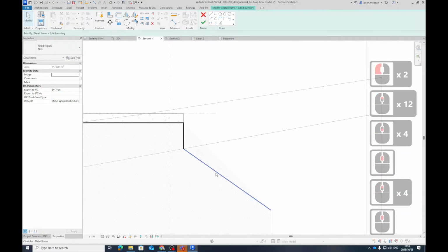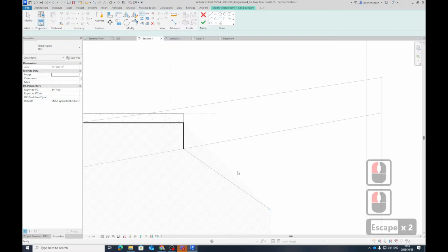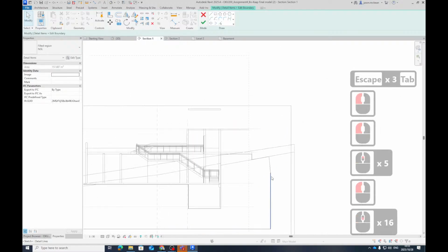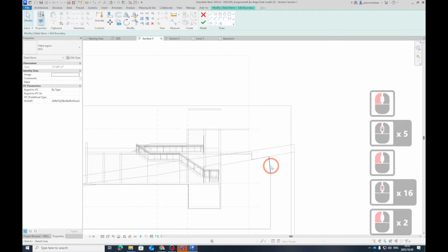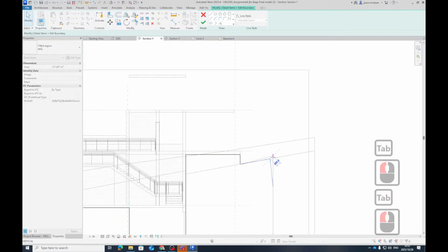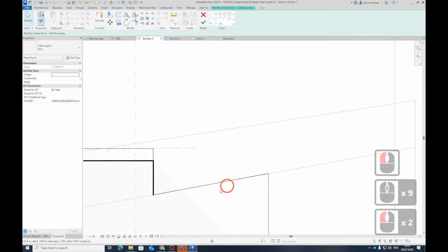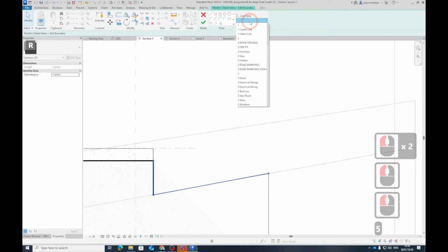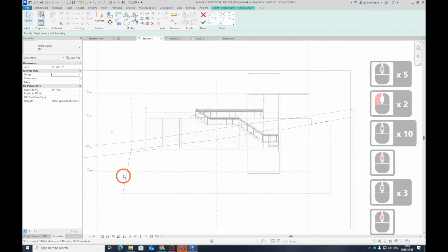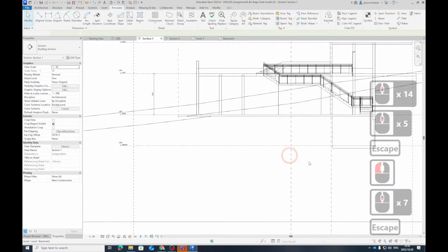Now your natural ground level. So I'm going to use split line again. I want this. Tab. I want this to follow the natural line because I can switch that off for now. Just maybe make this type. So tab again. I want this to line up perfectly. There, straight, line up, and then I pull this back down so it ties in with that, as close as you can. That's all line weight 5 again. So 5. If it's blank, it tells you there's multiple applied. Now, that's all you need to do. Here again, you can make your embankment look like it should. Done. Then remember, that's your natural ground line.